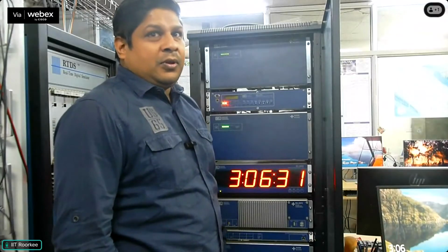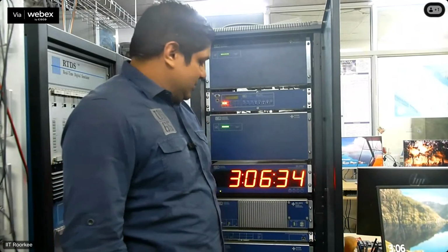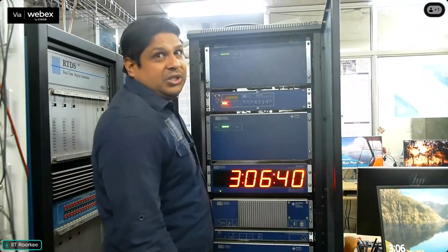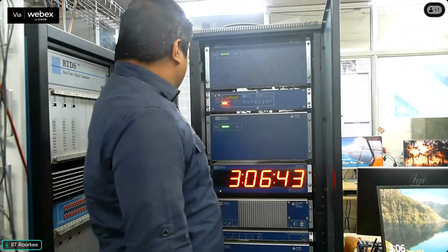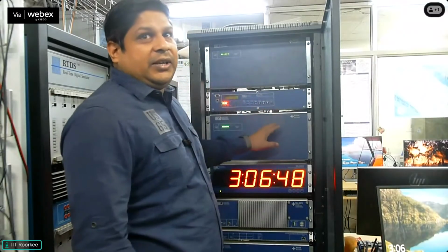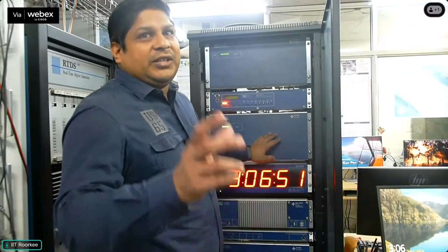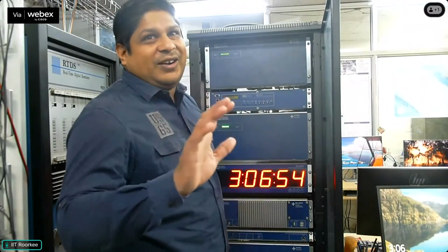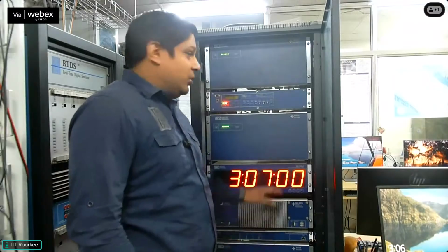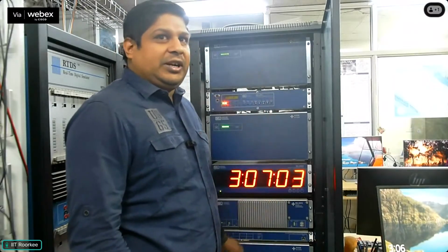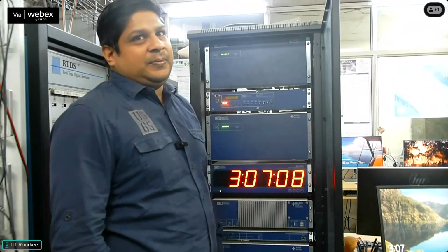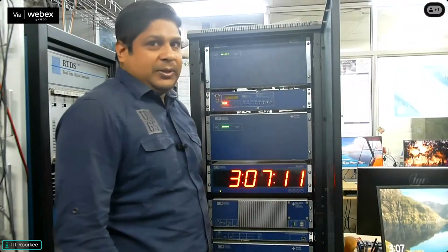What if we have to simulate more PMUs? Yeah, so we should have more amplifiers, or you can go directly using the GTNet card. That is connected to a switch, and the switch is connected to this PMU. So directly through communication channel we can, but that is a kind of simulation. There are no hard signals there. So we directly connect it to the PDC. So we can mimic that there are n number of PMUs out. Yes, so that we can do here.